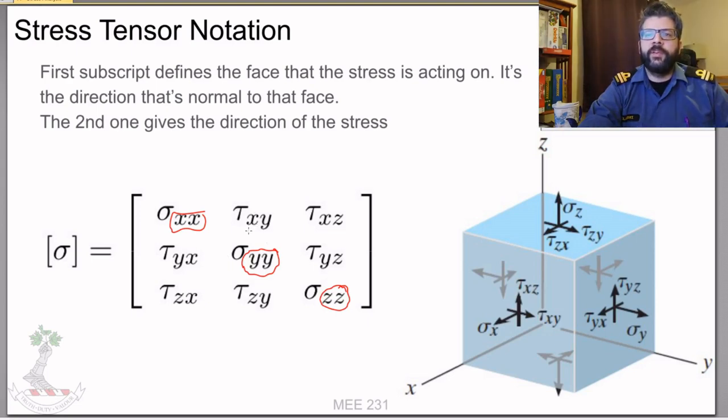Whereas if you have two different subscripts, then that's a shear stress. If, as shown here, you're only given one subscript, then that's implying it's a normal force. Essentially, instead of saying sigma zz, they just said sigma z, and you could figure out that because they only gave you the one, it is a normal force.